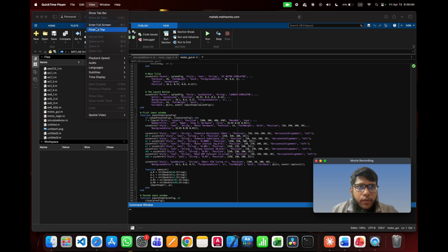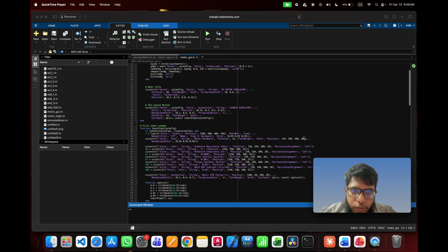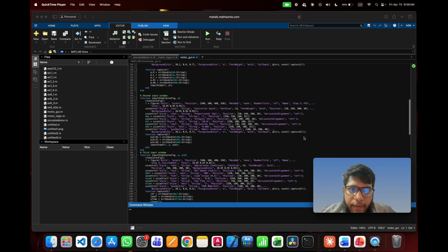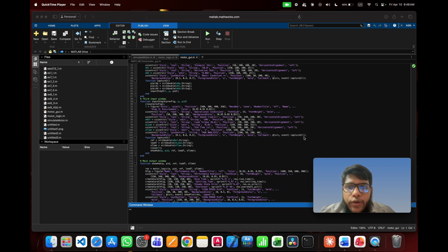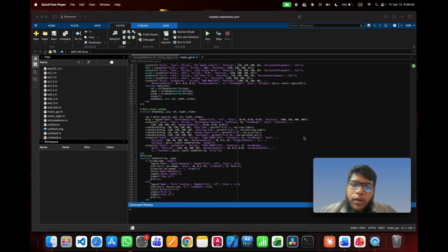Now I am going to explain the motor GUI. First you have the launch button. If you launch, in the first input window you have to give the hardware parameters like armature resistance, inductance and back EMF. In the second window you have to give the PID gains, proportional, integral and derivative gains. In the third window you have to give your references, target speed, load torque, etc. Then if you click, the output will be shown and you will have the option to see the plot.